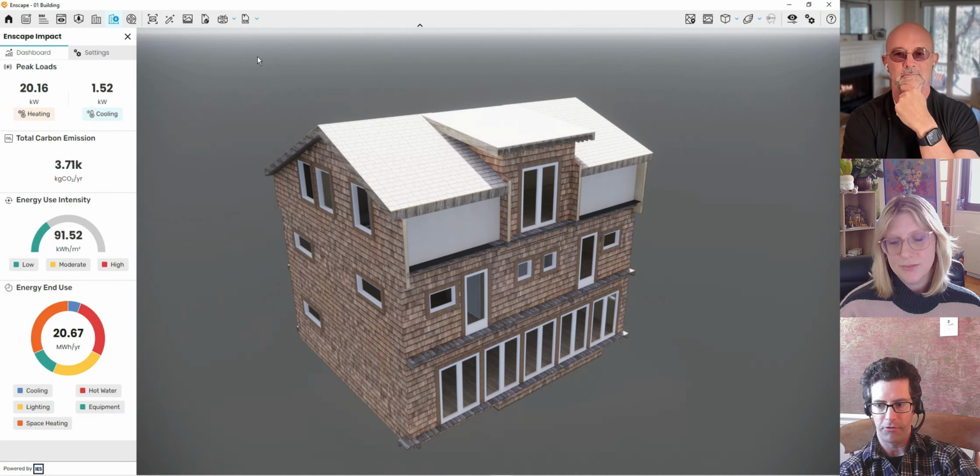Just turn it on. The trial is fully functional. You've got 2 weeks. Monica, one of the things you guys had mentioned is if you've got an aggregate site, like a campus project with a lot of little buildings, the best practice is you can have everything in there for visualization purposes in Enscape, but you should have multiple views saved off with section boxes around them in Revit to isolate each building.